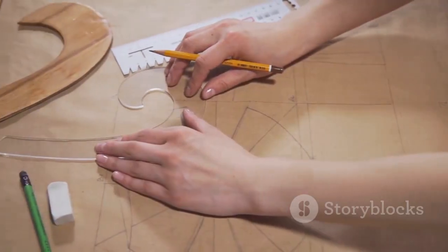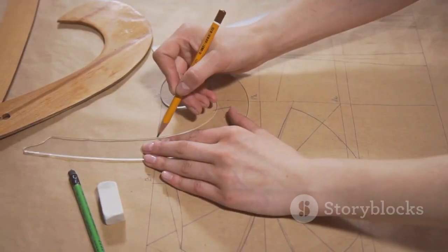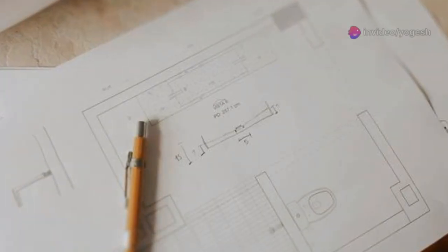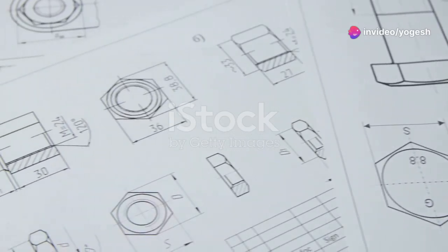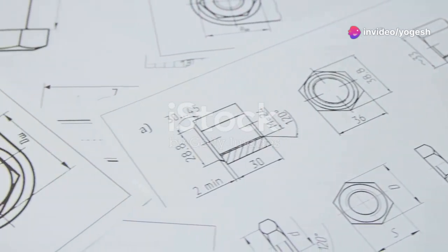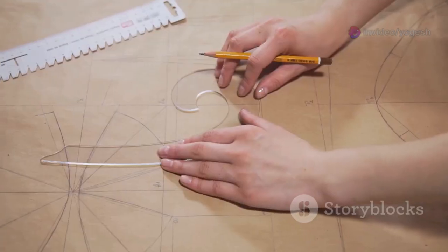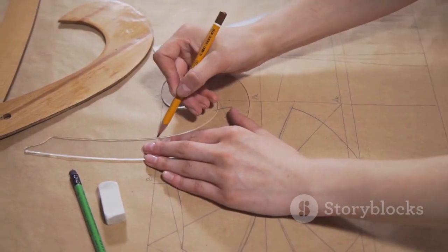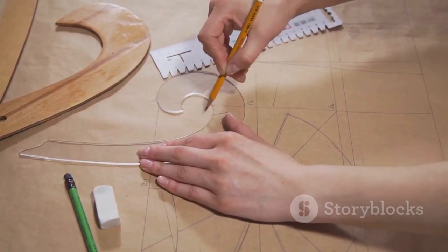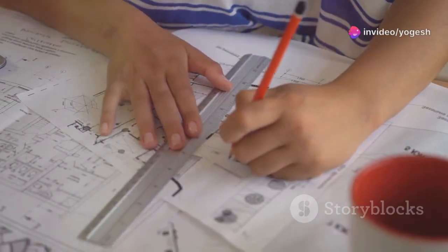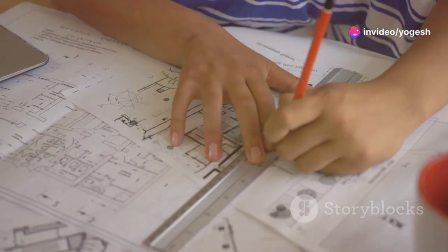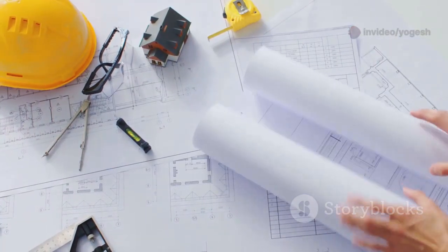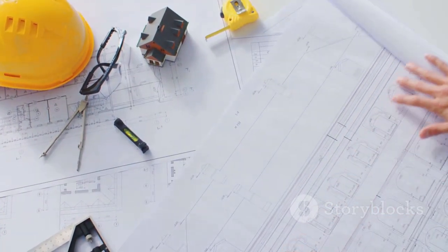Let's draw a primary auxiliary view, step by step. Start with your standard views, front and top. In the front view, the slanted surface appears as an angled line. In the top, it's foreshortened. Draw a reference plane line parallel to the angled edge in the front view. This is your folding line. From every key point on the slanted surface, draw projection lines perpendicular to the folding line. These lines map features from the front view into the auxiliary view.